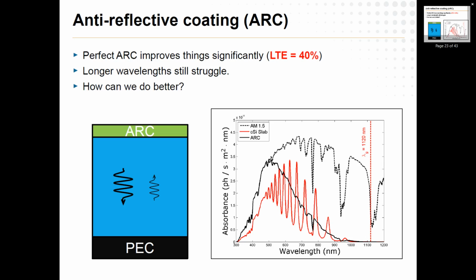So I have 1 micron of thickness this way, but I might have 1 million microns of thickness in the lateral directions, right? So basically infinite distance. If only I could get light to go these directions. So that's the main idea behind light trapping: how do I get light to go from up, down to left, to right?